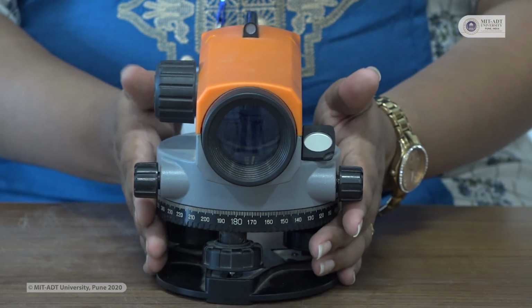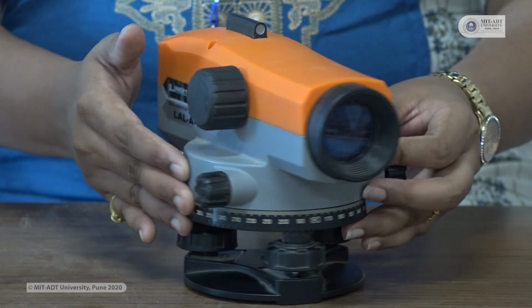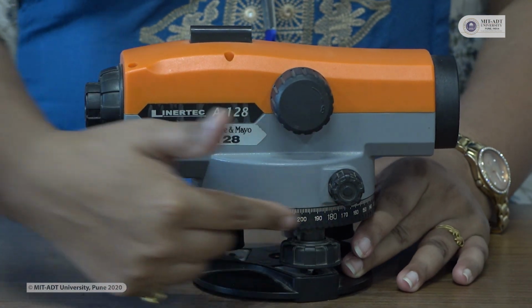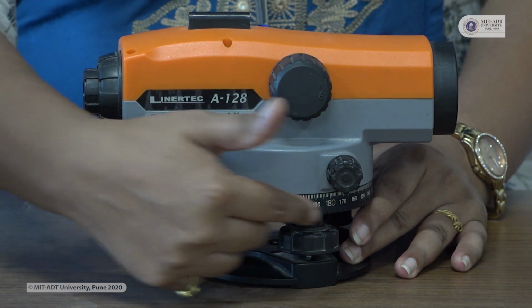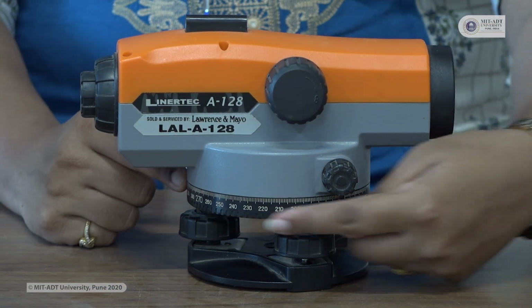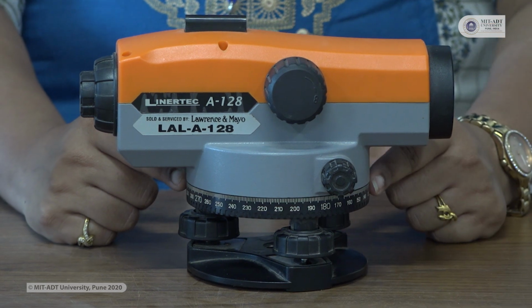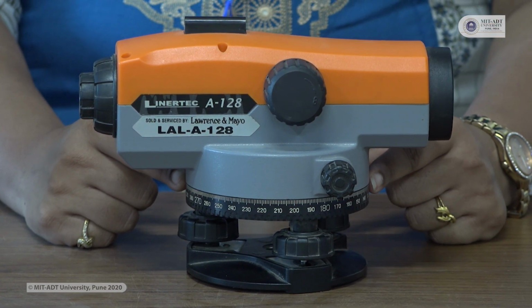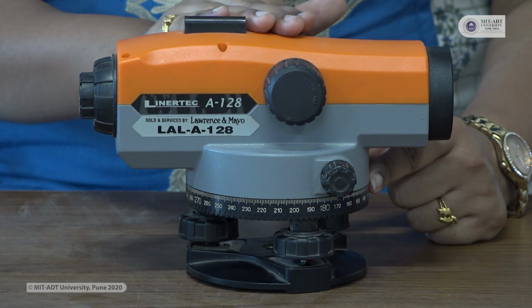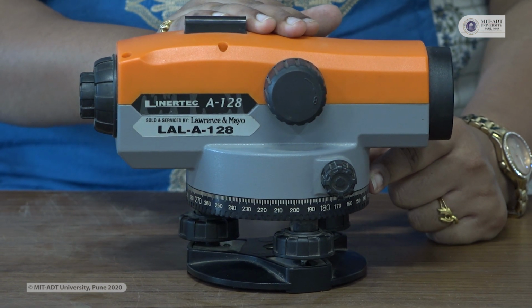After this leveling head, this instrument is provided with the marking of the readings. If you have to measure the angle between different points, then you can measure that angle by using these compass markings. These compass markings are in 360 degrees, and if you want to take readings with respect to the north direction, then a temporary supplementary north will be attached to this instrument, and you can measure the reading.